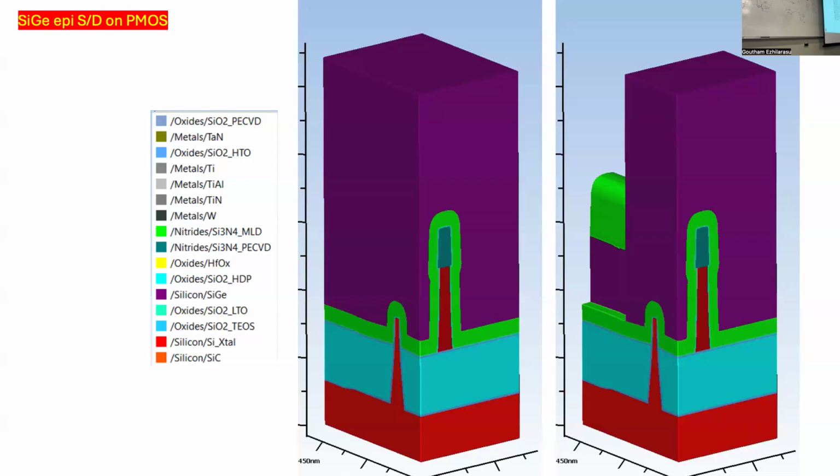And then if I need to create silicon germanium here and I need silicon carbide here, these are grown epitaxially, right? Which means they're put inside some furnace. They're heated to high temperature, right? Which means you cannot do this with an organic mask. You need some inorganic mask to prevent the silicon carbide, silicon germanium from forming. So what you do is you have this nitride oxide mask everywhere, and then you just open it up in these regions.